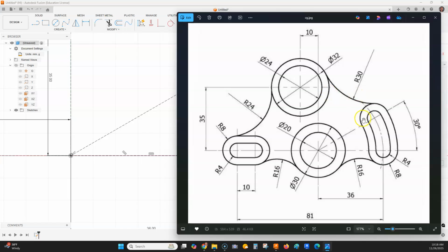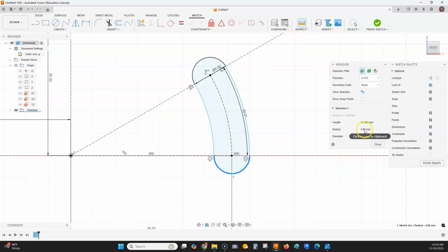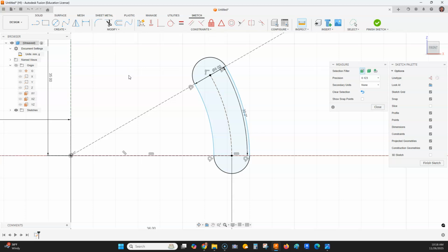And if I go back, I told you to put in like a distance of 8. That's the diameter here. So we're going to go back and take a look at, we have radius of 4 here. And how could we possibly check that? We can go up to the inspect tool, click on one of our arcs down here, and it'll say a radius of 4, a diameter of 8. So what we need is we need one that has a radius of 8. So when we drag out, we're going to go 16 on the next one.